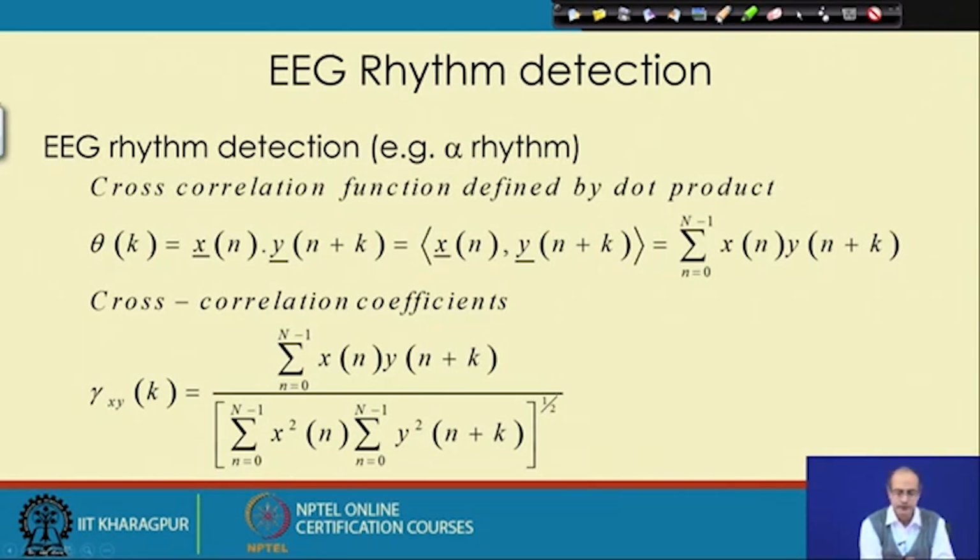the cross correlation function. Okay. So, the cross correlation function is nothing but the dot product of the two vectors x(t) or x[n] and y[n]. There are different notations to write that. Here we are just showing the ways we can write that. We can use triangular brackets, or we can write it as a dot product. The essence is that for the vector x[n], we are using a notation where below we are giving a bar.